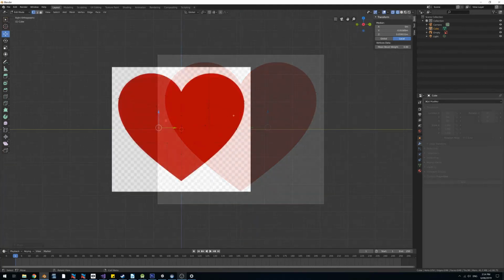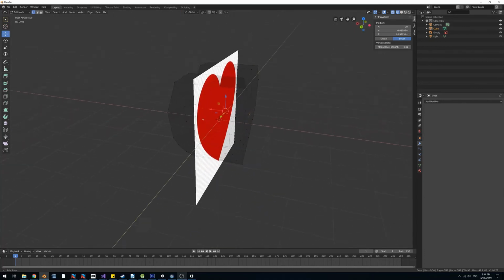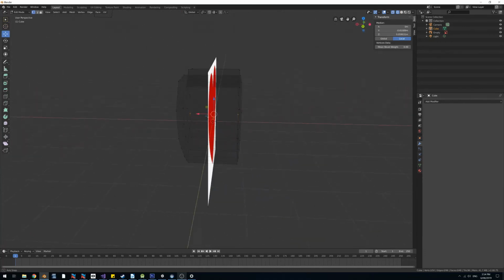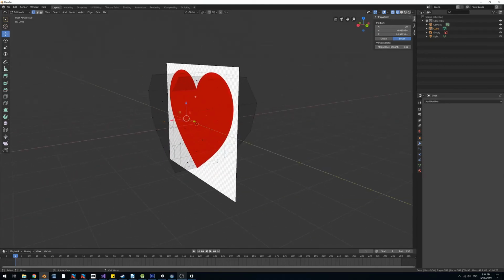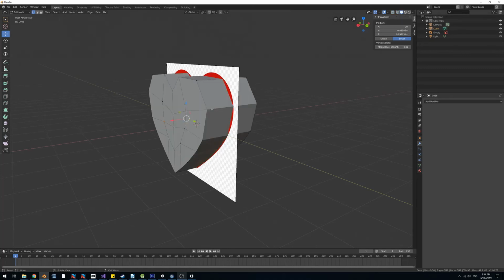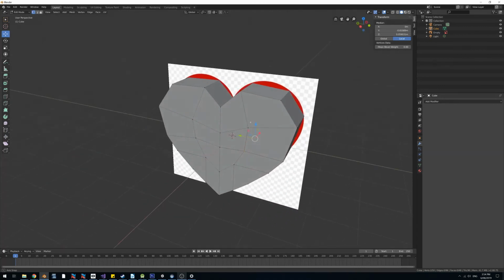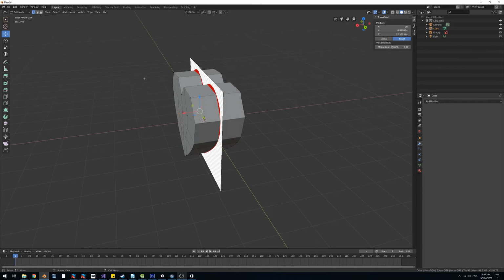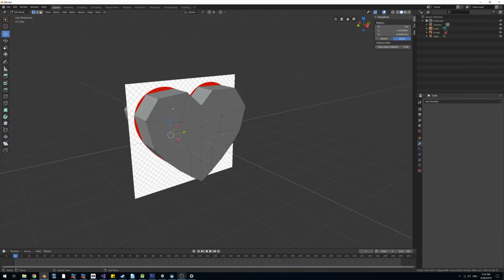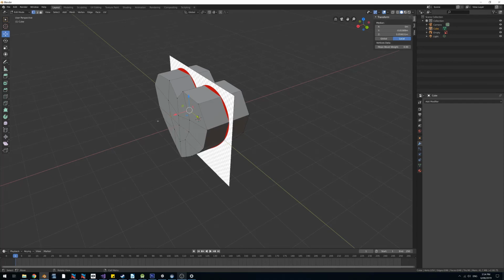So now if I go back into my perspective mode, by middle clicking the mouse button, we can see that a heart has somewhat appeared out of this mesh. Now it's still a little hard to see because we have it in wireframe mode. So I'm going to select shaded mode again from the top right up here, and now I can see this mesh a bit better. And it does look a lot more like a heart, but it's still somewhat basic and unconvincing. And what I want to do now is subdivide these big meshes, these big faces, should I say, and make them smaller and smoother.